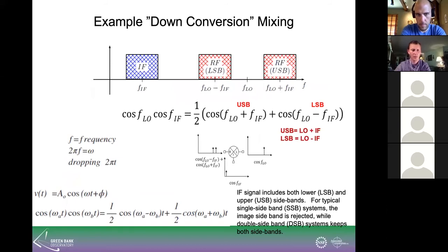Look at it schematically across the frequency. Here it shows an example where you have an LO here. Your sky signal, you have a lower sideband and an upper sideband, and the intermediate frequency is the difference between your sidebands and your LO. So your IF frequencies are here. So this is a case where you're down converting, basically. You're observing way up here in frequency. You mix it in with a high LO frequency. The difference between the LO pair is the IF frequency, and you get the upper and the lower sideband. So what you get out is a combination of both the upper and lower sideband.